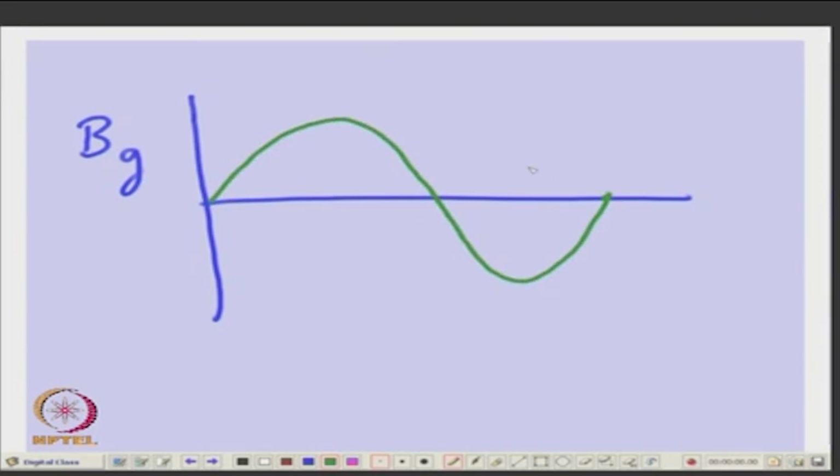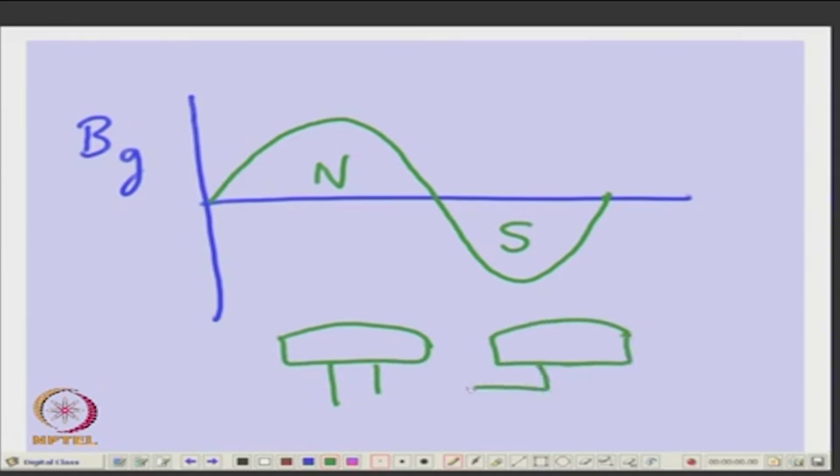through the magnet. So, one you can call a north pole, another you can call a south pole. So, you have a magnet located like this. Is it not? So, at any given position the distribution of flux density in the air gap will be sinusoidal. Unlike in the brushless DC where you expect it to be nearly a square wave, but may not be fully 180 degrees, it may be 120 degrees also.